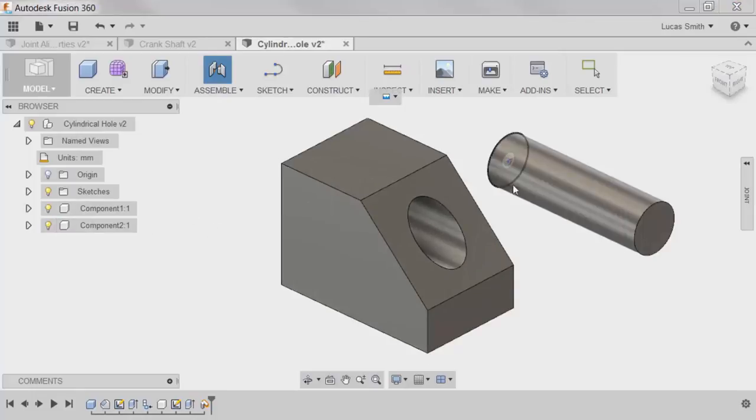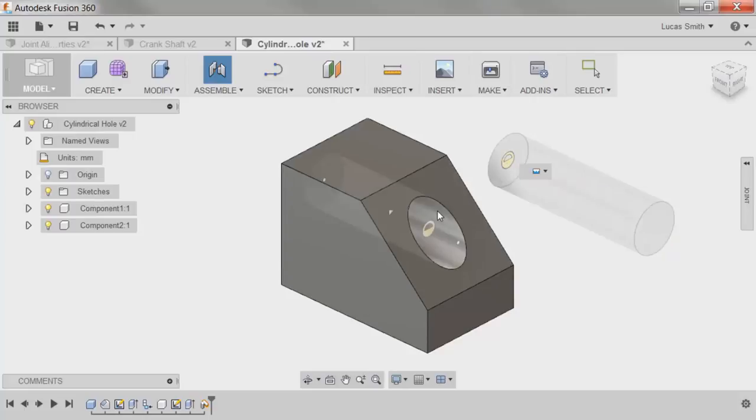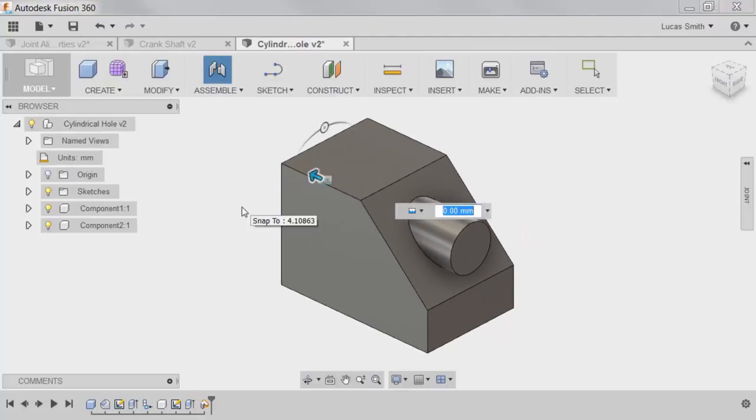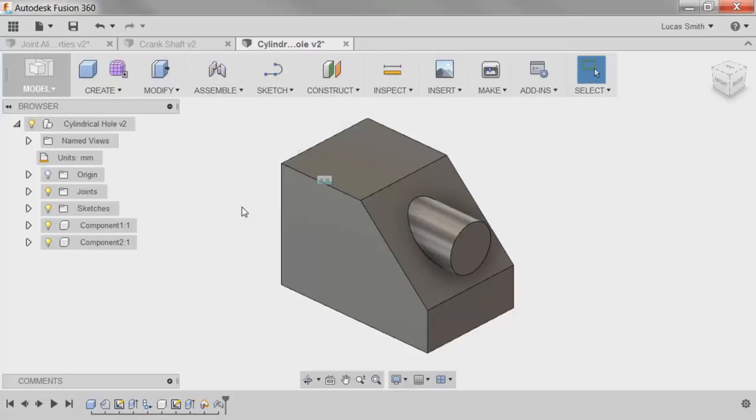Whenever selecting a joint location on a component, keep in mind that it will snap to the other specified point on the other component. This makes it extremely important to choose the right location, taking advantage of the snap point symbols along the faces and edges of components.